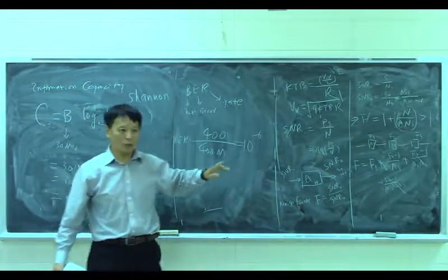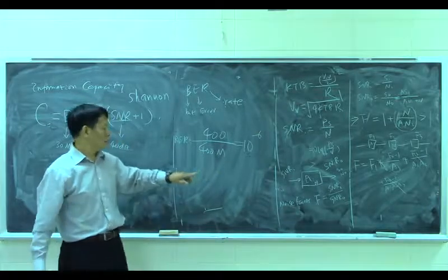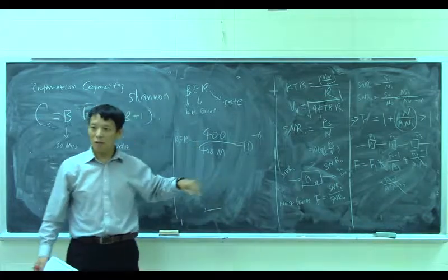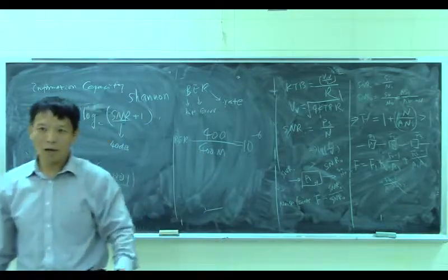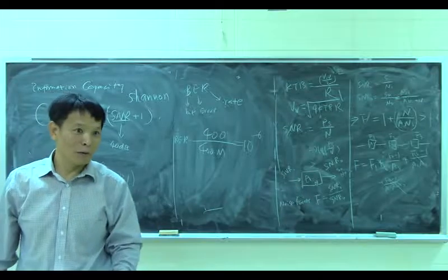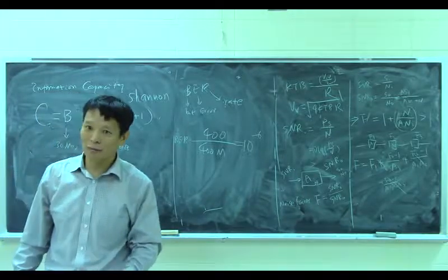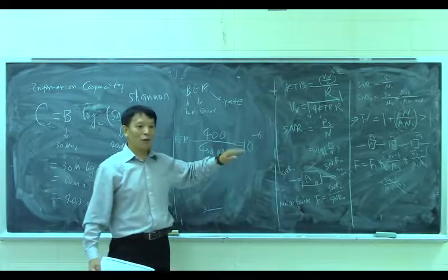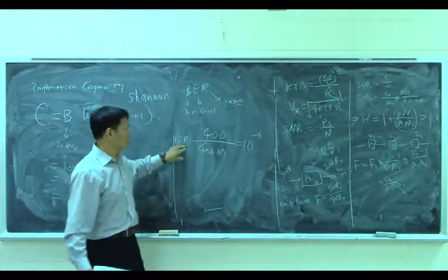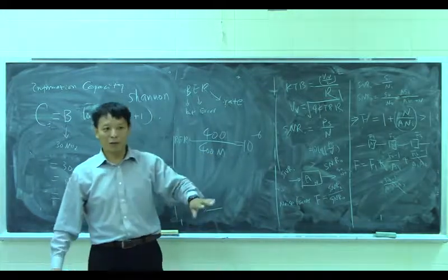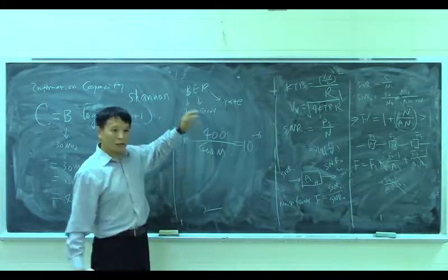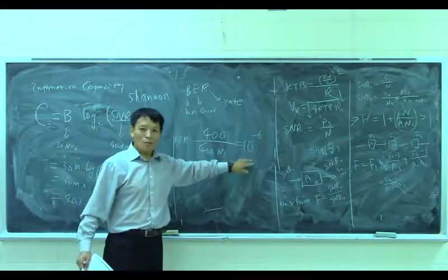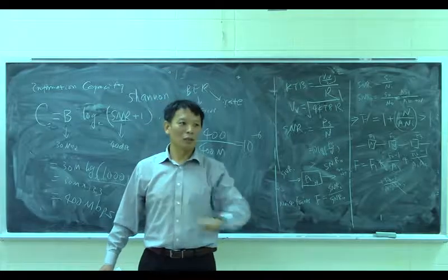So the higher the quality, the smaller the bit error rate. If your transmission situation is very bad, then your bit error rate will be large. For digital phones, everybody has a digital phone. You don't have any analog phone anymore, right? Who has any analog phone? No one. The good thing with digital is that if your signal-to-noise ratio is good, the quality is perfect. If the signal-to-noise ratio is reduced past a threshold, you receive nothing.